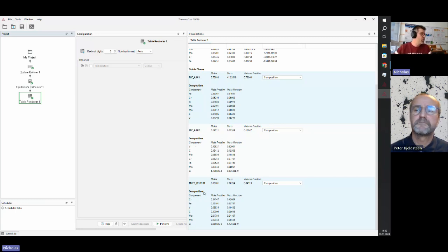And in addition, we've also got some M7C3, which is basically a chromium carbide, one of the famous chromium carbides. Everybody knows them. And again, it's not just chromium 7 carbon 3, right? It's got quite a substantial amount of iron in there. So it's not a pure M7C3.